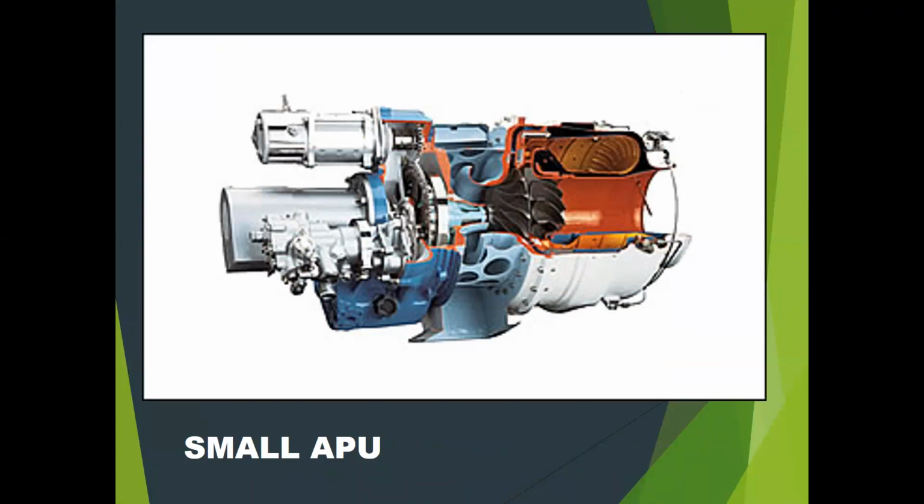Some small aircraft, if they're a DC aircraft, will have a starter generator on them. Then pneumatic is bleed air that we can pull off of the APU. And then in some aircraft, these also can be used to run a hydraulic pump as well, or a pneumatic pump to provide things like reservoir head pressure. And in the next unit, we'll look at hydraulics and we'll talk about where that's used.